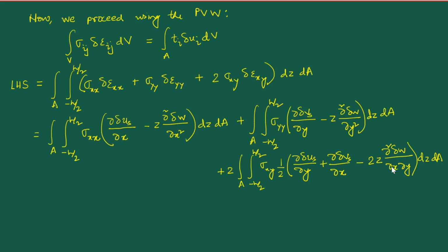So none of these terms, this term, this term, this term, it is not at all multiplied, meaning it is not at all coupled with either the us or the vs. And that is good news for us in exactly the same way it was good news for us back in beam theory, where such kind of absence of any coupled terms indicated that physically the stretching and the bending were completely decoupled, and we had seen that. It was as if we were simultaneously considering two separate problems, the stretching problem and the bending problem.